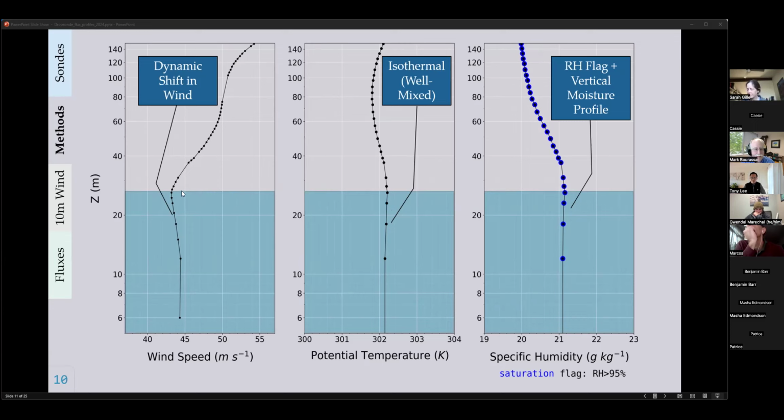If you have the displacement height, you have your log layer, and it's going to extrapolate to something pretty far away from it at the displacement height. So you want to be maybe 1.5 times the displacement height, whatever it is. If we could start figuring out what this displacement height is, then that would help you get the height of the layer where you'd want to look at it. When I was doing wave tank work, 1.5-ish was a cautious estimate for throwing out everything that wasn't going to fit a profile.